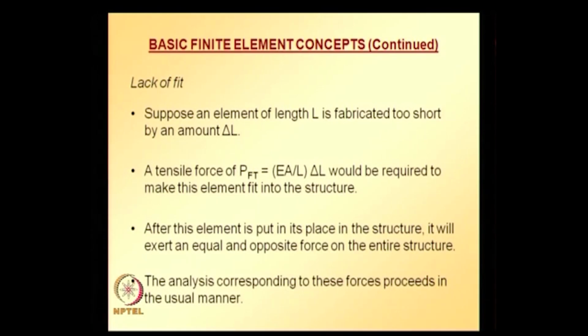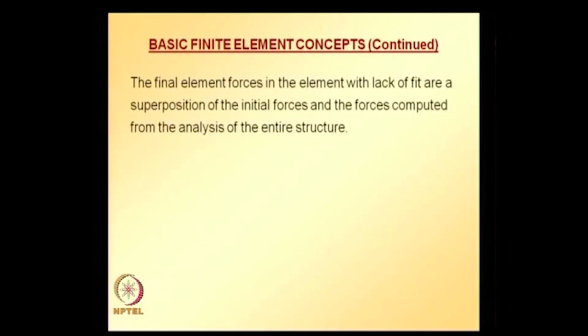So the analysis corresponding to these forces proceeds in the usual manner, except that at the end, when we are calculating element forces, we need to add the forces due to lack of fit. So the final element forces in the element with lack of fit are a superposition of initial forces and forces computed from analysis of the entire structure.